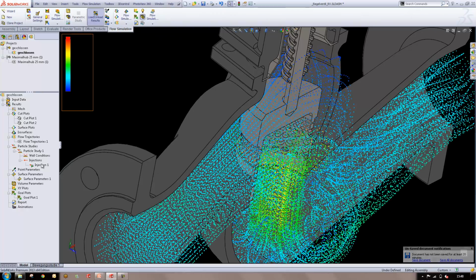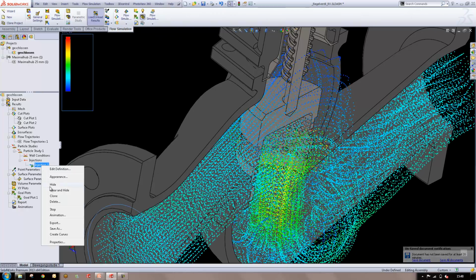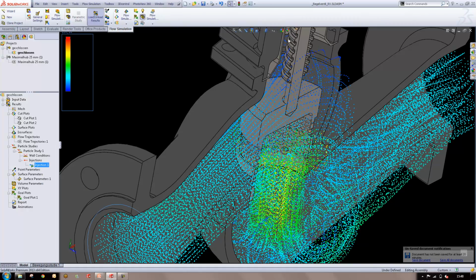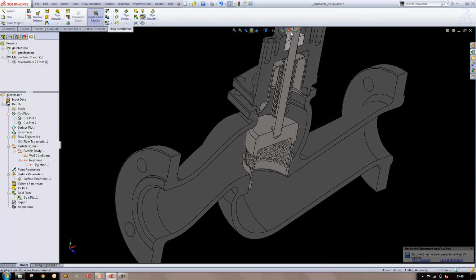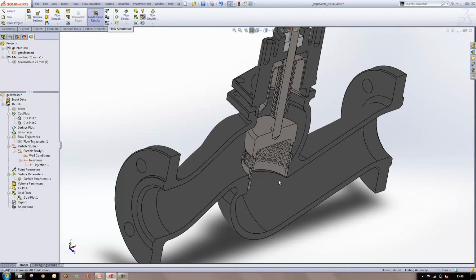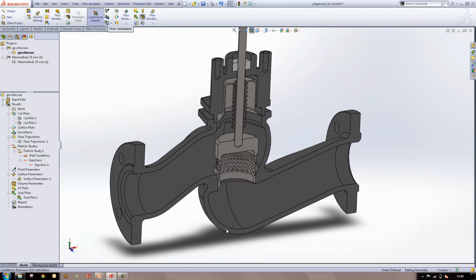As with all of the other plots and information that we've gathered out of here, we can change the values that we're painting that with. So in this case, that was painted with the flow velocity. We can change whatever value it is we want the colors to represent there, and that can give us a really nice way of analyzing not just temperature, but also flow velocity and turbulence characteristics, etc.